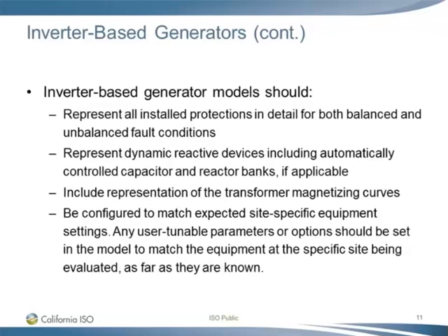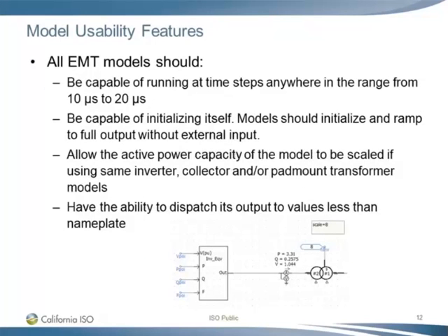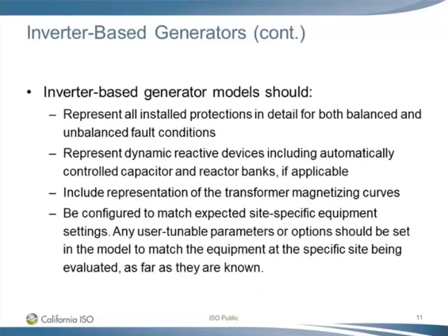Finally, inverter-based generator models should be configured to match expected site-specific equipment settings. Any user-tunable parameters or options should be set in the model to match the equipment at the specific site being evaluated as far as they are known. For example, if the facility is in power factor control mode, it should be represented as such. All right, next slide.